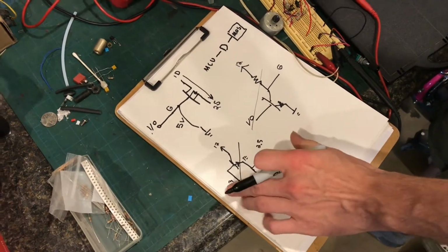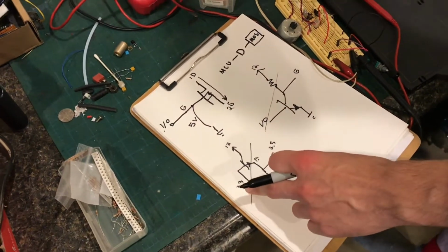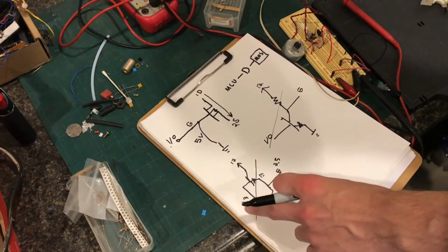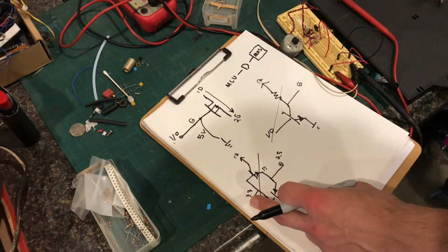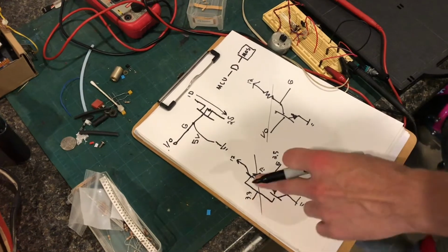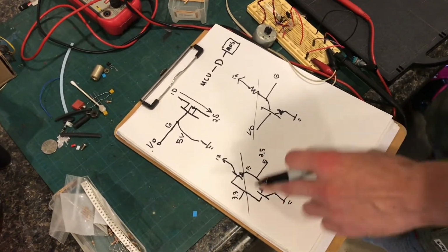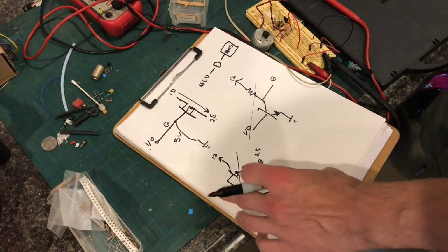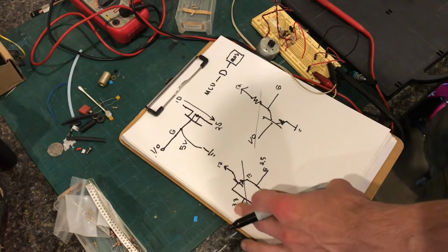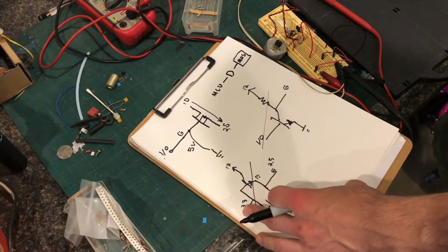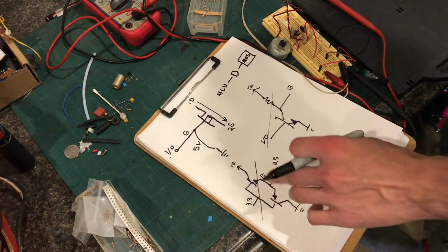In that case, if I had a higher voltage at the input to the driver, then you could use something like this to drive a really big MOSFET with a higher voltage but a very low current device. But I actually don't think that would work great with low voltage logic.